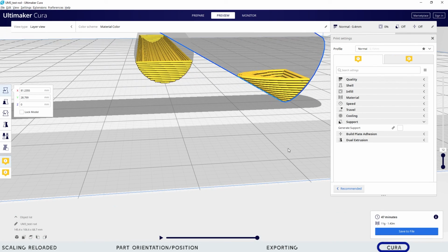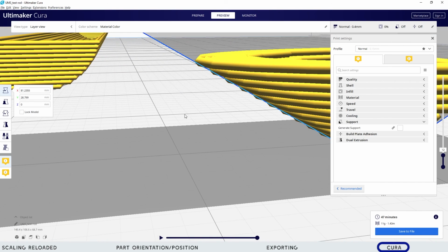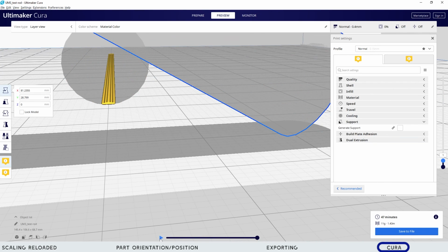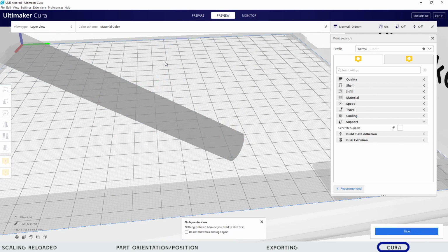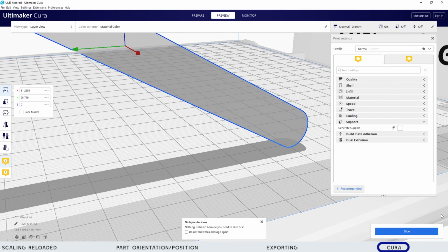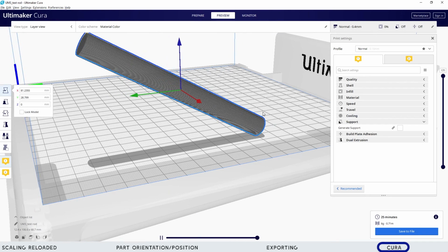We can see that this part, although it's not much of an overhang, I'm trying to get to it. It's not much of an overhang from this layer here, from layer 11 to layer 12 here. It could handle that much. But if you think about at layer 1, this entire component, this entire piece here, I'm going to get rid of this here. This entire piece here is touching at that single spot. I hit slice again. And there's no way that that little bit of material is going to support that entire thing.